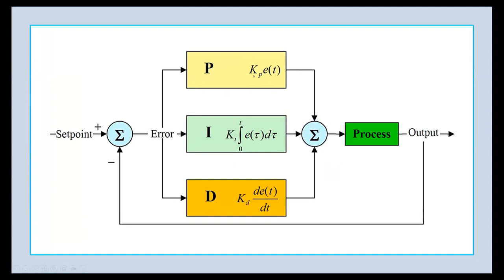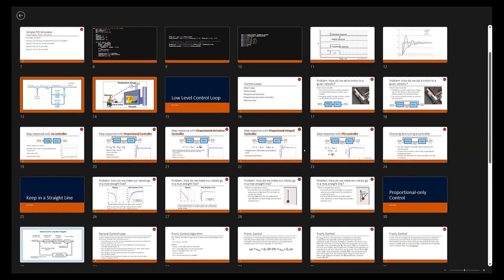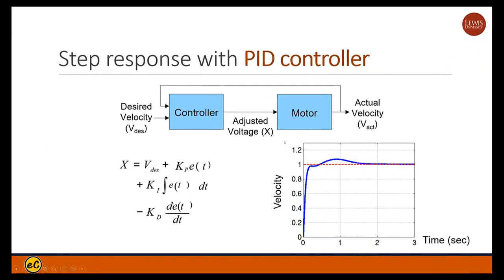You can use so-called RLC components, resistive, inductive, or capacitive components, to design your PID if you use an analog electronic system. You can also put all the control in a digital loop. Nowadays people tend to use a microcontroller to perform this PID.